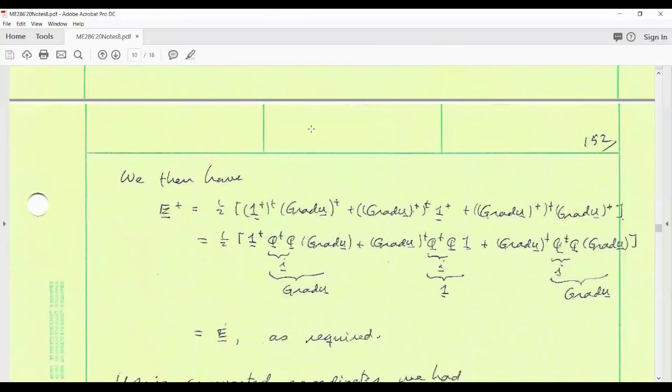Okay, let's go back to the strain displacement relation. We all know that the strain should be insensitive to superposed rigid motions. Let's make sure that it is. After superposed rotation, E plus would be the same as E, except everything would have a plus appended to it. Every variable would have a plus sign on it now. 1 plus is Q1, and take the transpose of that, you get this. Q is the spatial rotation. Q transpose Q is the spatial identity.